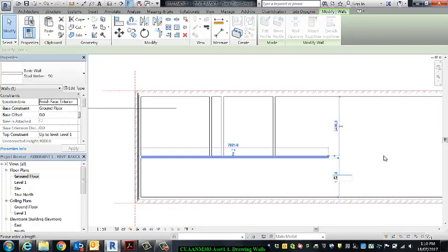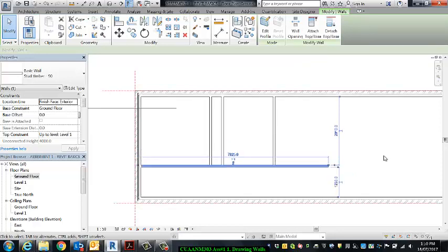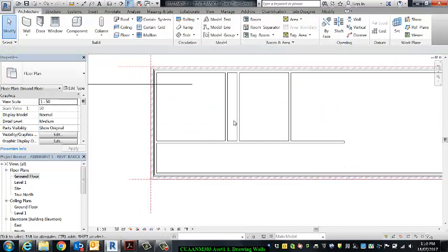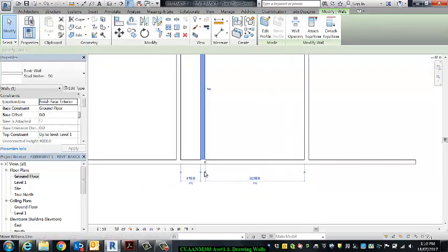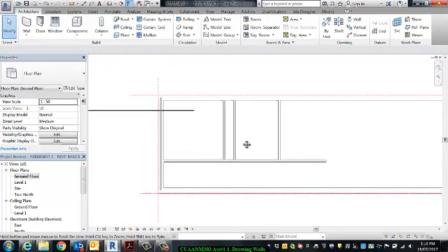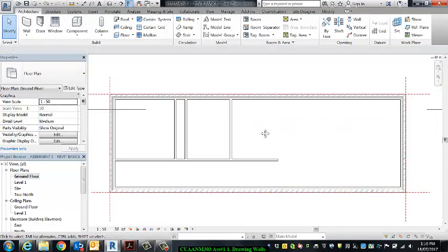1230. Okay, if it's not going to the bit that I want it to, and I'm going to have trouble making it behave itself now, but what I can do, just as an example, is see these blue dots? I can click. I'm going to hold down the left button of my mouse, holding it down and then releasing it. See how that's going blue? I'm going to release that and now it's dimensioned to the bit I want and I can click and adjust. So that's how you adjust the temporary dimensions.